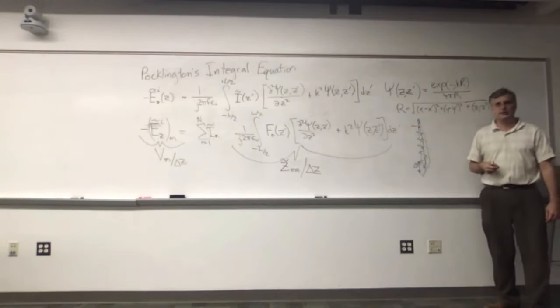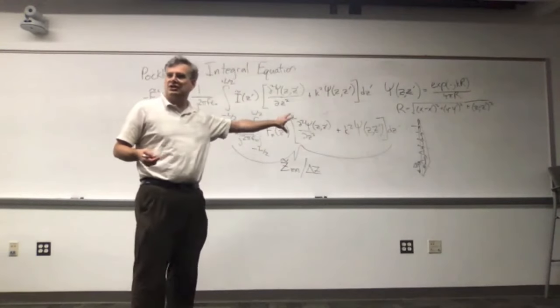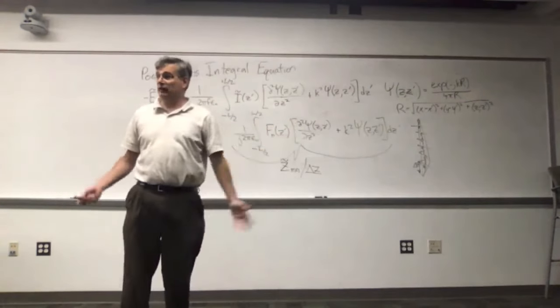So now you see why this integral equation business is so difficult. It's hard to solve for something under the integrand. Because if this was a problem that required 500 sample discretizations of a fairly large electromagnetic problem, even if it was a simple wire antenna, that would mean I would now have 500 squared computations to make here. Then I've got to invert the sucker.